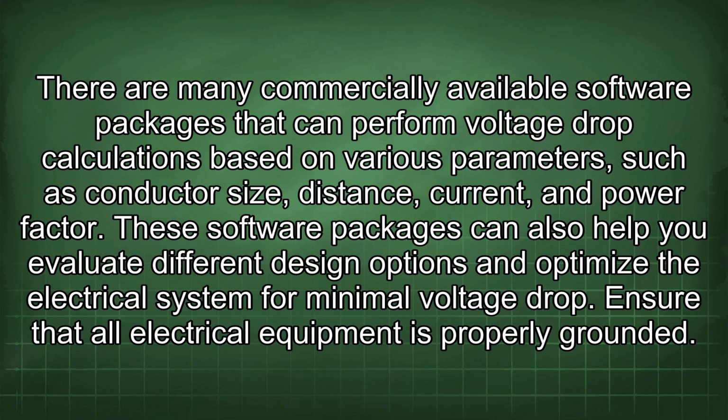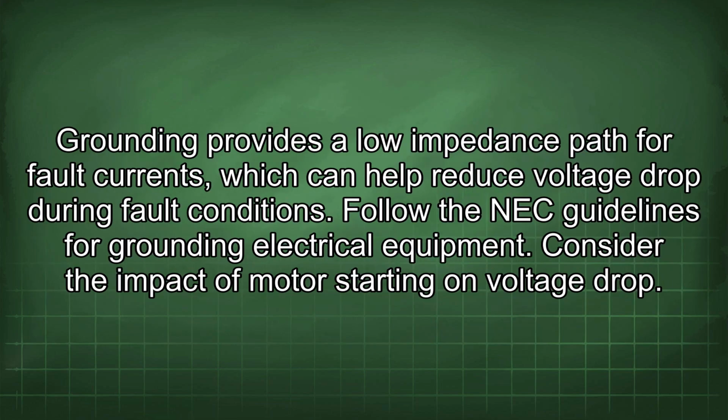Ensure that all electrical equipment is properly grounded. Grounding provides a low impedance path for fault currents, which can help reduce voltage drop during fault conditions. Follow the NEC guidelines for grounding electrical equipment.